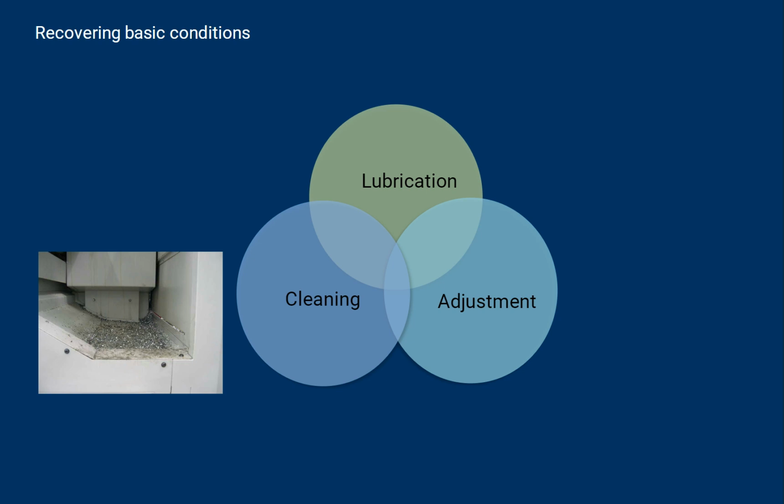These substances can cause abnormal vibrations, pipe blockages, abrasions, burns, faulty operations, and decreased precision, among other problems, leading to stops and breakdowns in sliding parts, hydraulic systems, electrical systems, and instrumentation. Equipment deterioration due to lack of cleaning is a typical example of forced deterioration. Cleaning does not aim to enhance appearance. Its objective is to establish basic equipment conditions and reveal hidden defects to eliminate breakdowns.